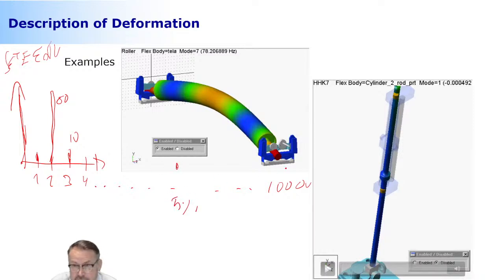And the rest is like 0.0000%. And if it is 0.000%, it doesn't make much of a difference, so you can easily ignore them. That's exactly what is done in model reduction technique. The ones that contribute very little, you just let them go. You don't care about that. That's how you can come down from 10,000 degrees of freedom to whatever number you want. And it's amazing that often 10 is enough. Then it gives you 98% of the strain energy, which is a good estimation. It is true you're losing 2%, but that's still okay.